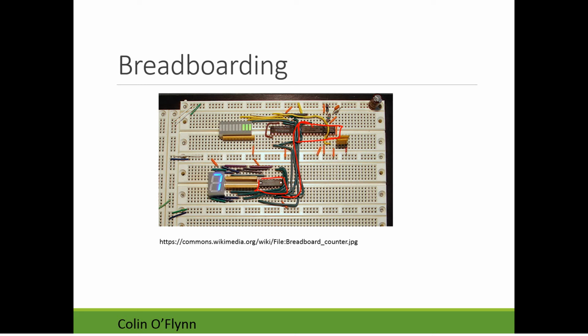The second problem is that a lot of components no longer fit into a breadboard. If you look at what are called surface mount devices, which are really small parts with the leads coming out of it, there's no way to easily mount them. You've got to mount them on another circuit board and put that in. And another issue is if you start doing high speed or analog circuitry, it can be very difficult to get sufficient performance out of a breadboard.